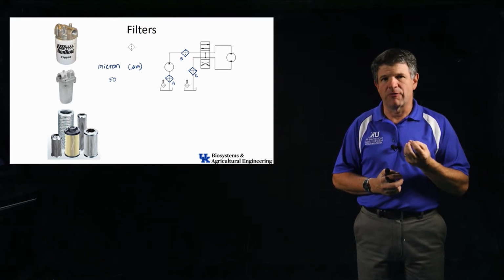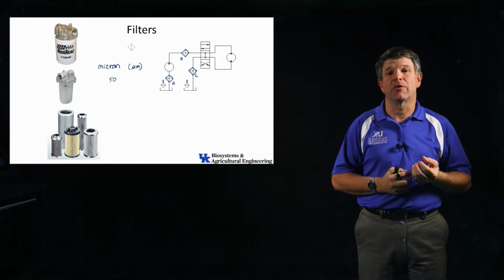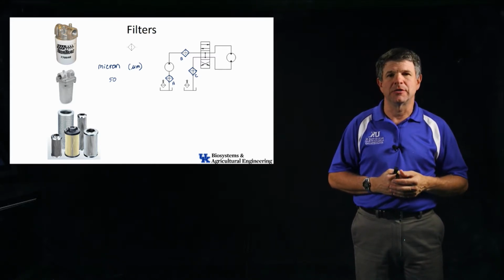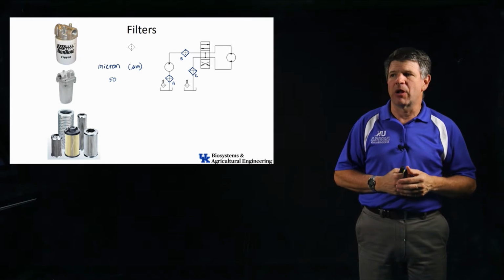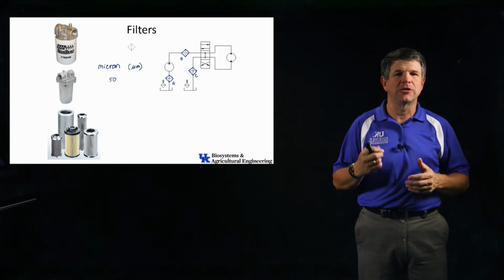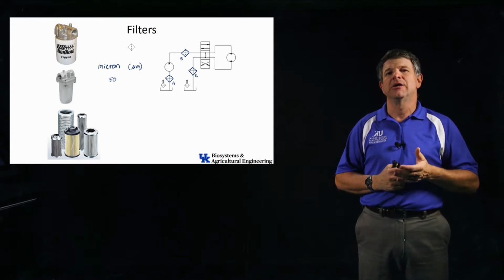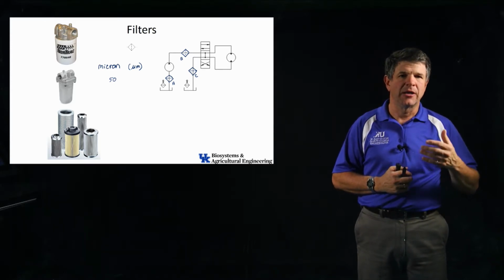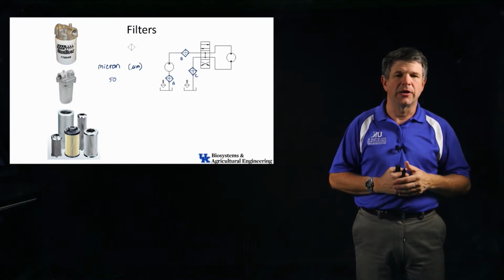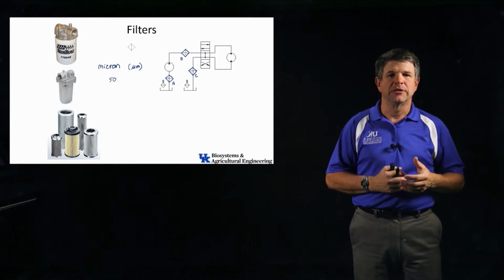That's going to be a smaller filter. We're going to try to keep our reservoir clean. Hopefully we'll manage the reservoir in a way that we don't introduce dirt into the reservoir as we go. So that's the more logical place to put a second filter. So typically a larger filter in position A to protect the pump, keep the big chunks out. Position C then is the smaller filter, the 50 micron type, to clean things out.